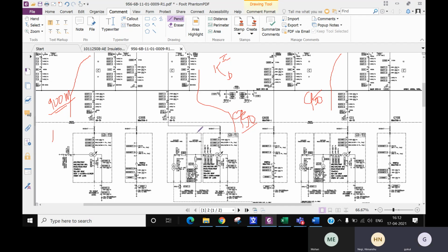Like, is it recommended only for high voltage? It's not like that. If you have a transformer in your system, at bare minimum you have to do the ferroresonance. Sometimes the clients may ask. Can they do this in ETAP? ETAP we can't do it, because ETAP is not the right tool for ferroresonance. The EMTP tool is the right tool.